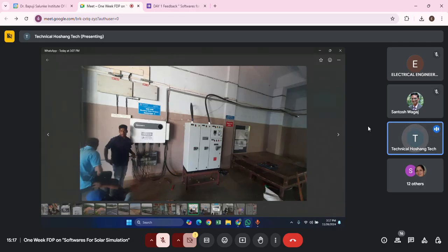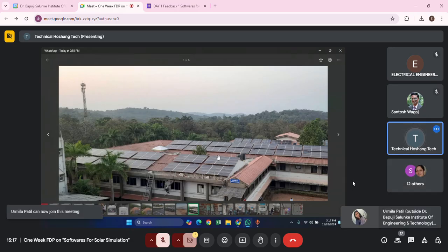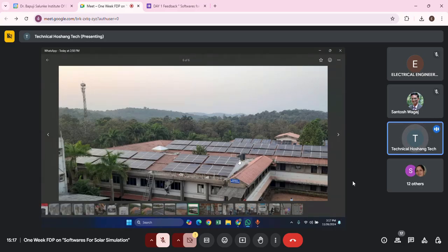The main thing while installing solar panels on the roof is how you design the layout and in what way you do it. While stacking the panels, you have to properly see the ground surface and whatever angle you have. In our case, we had almost 19.6 degrees of solar angle available, so we only needed to worry about the upper edge of the solar panel. While fixing, we increased it by 1 inch so that we get a 20-degree angle, and we have installed 670 panels for a total of 240 kilowatt.